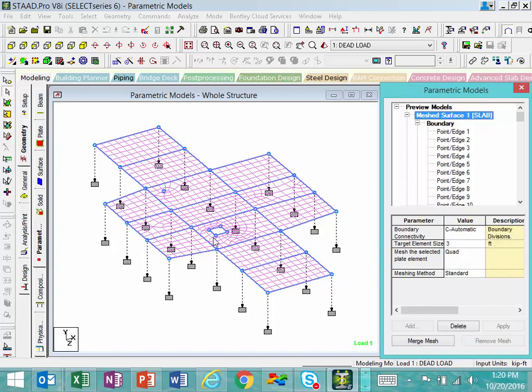Now, in addition to being able to very easily model holes graphically, and to consider internal points as density points, you can also create additional density points. So let's say, for example, maybe I have a concrete wall, and I'm just going to use these two nodes because it'll be easiest to show. Say I have a concrete wall running diagonal from here to here, and I want connectivity between this slab and that wall. Now that wall isn't exactly in the model yet, but I want to connect this slab to that line so that it'll make it easier to model that wall later.